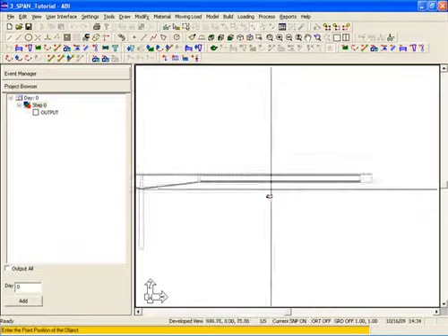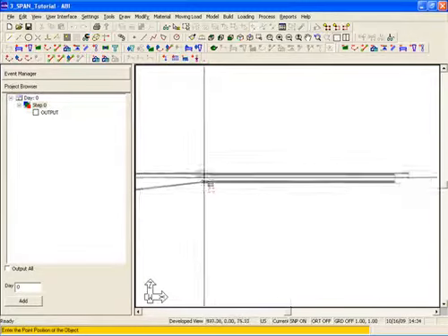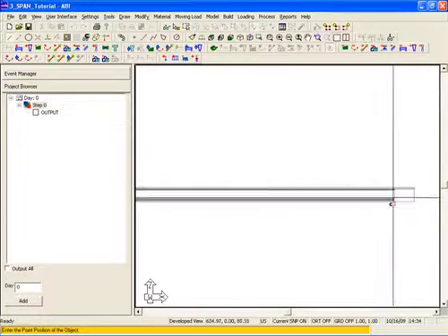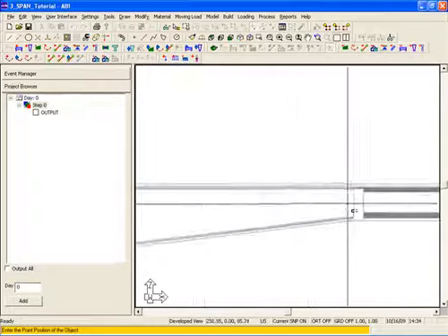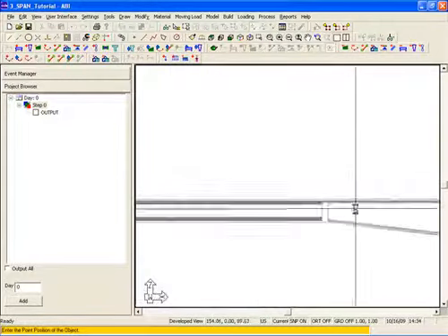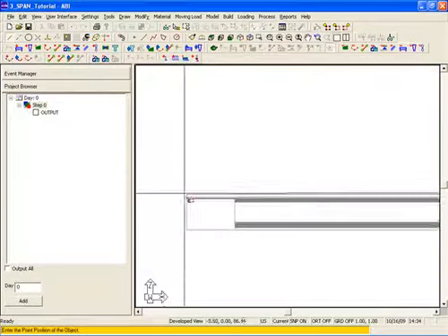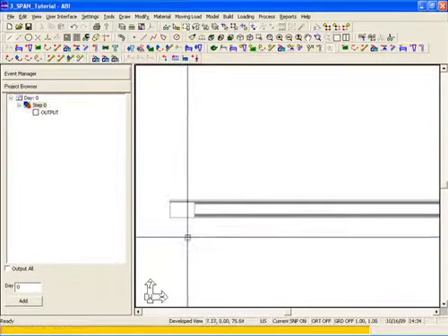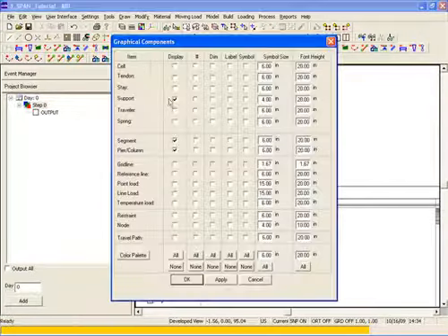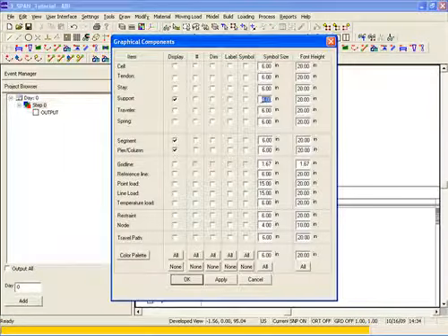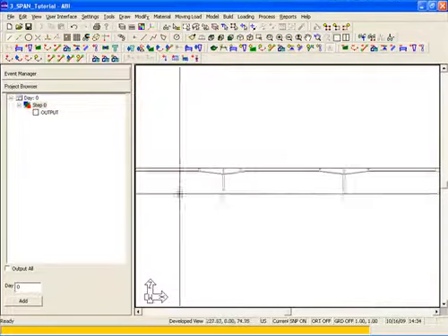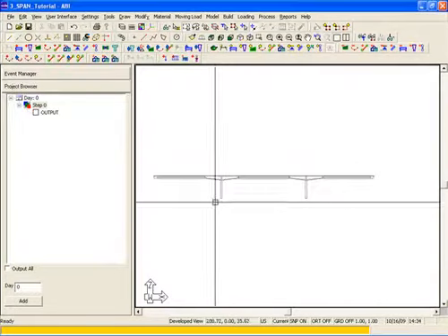These supports will represent any false work or shoring needed during construction. And finally, the left side abutment. To change the symbolic size of the supports, we can go to the Select Set View Items, and at Supports, we're going to go ahead and change the symbol size to 15 inches. That allows us to grab the supports easier when we go to modify and when we go to install them.